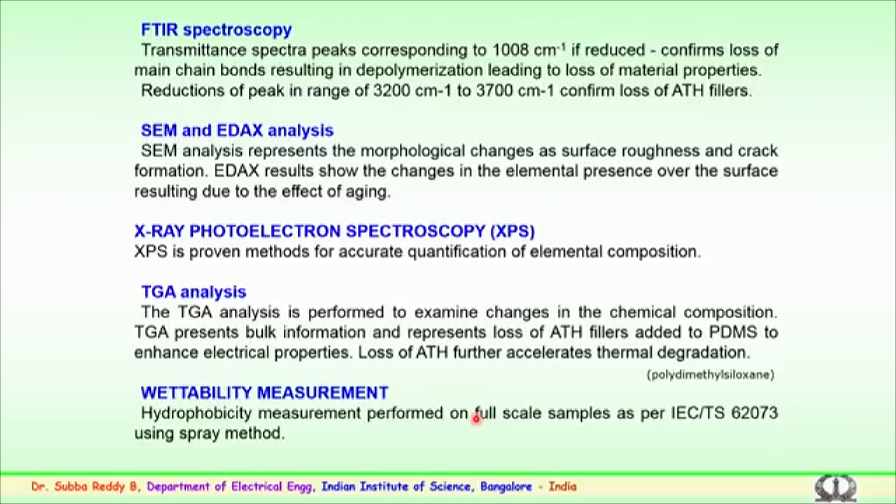The other is the wettability measurement, known as hydrophobicity measurement. Hydrophobicity measurements are performed on the samples, which could be slabs or full scale samples. This is carried out as per IEC 62073, and there are methods for both.